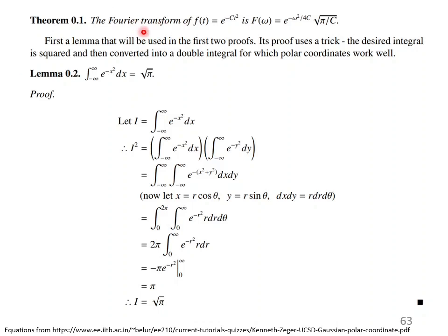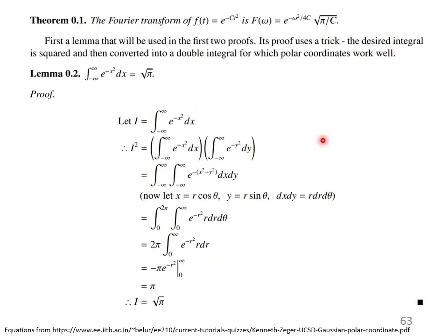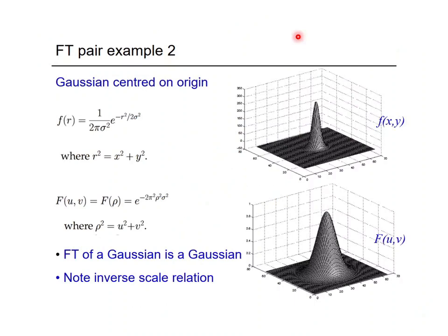The Fourier transform of an exponential term is still an exponential term. So let's go back here. As we mentioned before, the Gaussian filter or Gaussian distribution is a separable filter. It can be separated into the x and the y axis. Once we prove the Fourier transform of an exponential term is still an exponential term, then for the x-axis, the transform result is an exponential term, and for the y-axis, it is still an exponential term. So the result is also finally a Gaussian distribution.